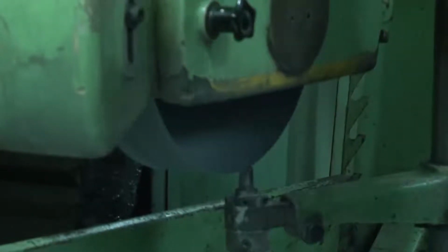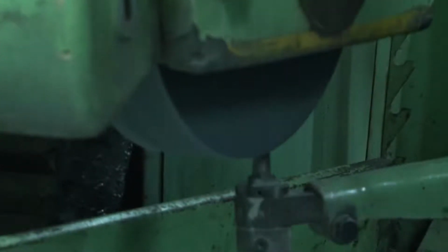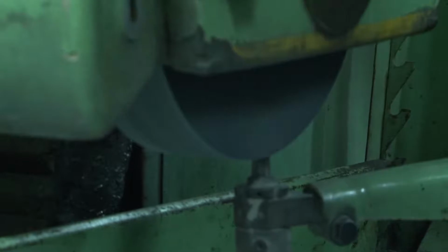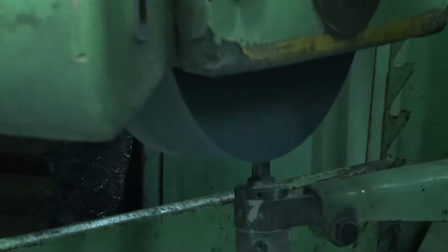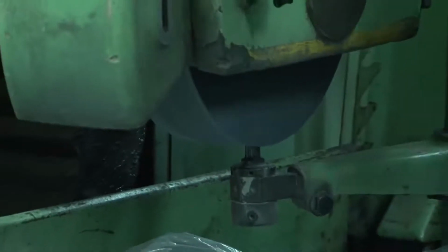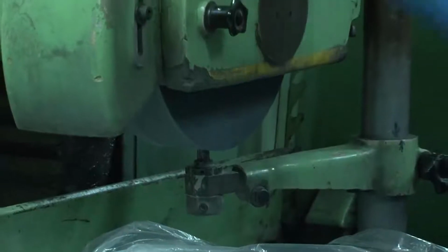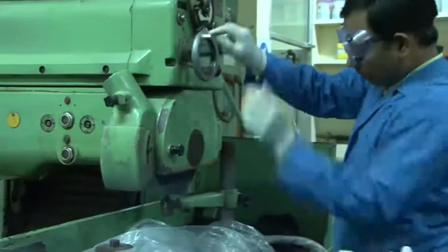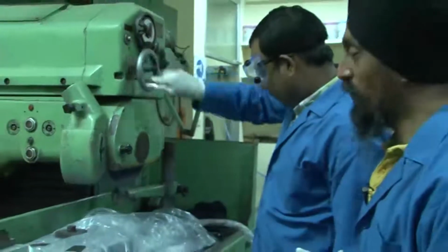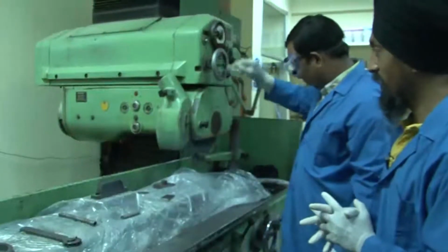See, he has already given 10 micron feed here. We call it feed; actually this is the movement upward. And he is now bringing the wheel to this side. That is the transverse movement, as the wheel is dressed. We will not run it only once; there will be multiple runs. This is recommended by the grinding wheel manufacturer. He recommends these various parameters.